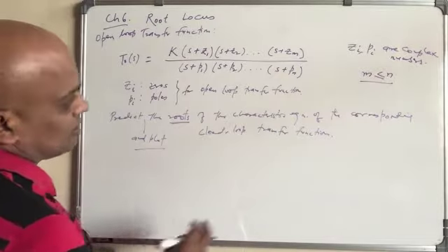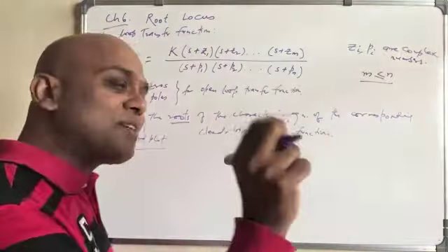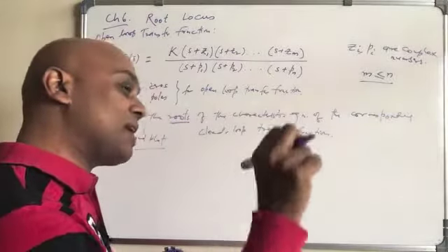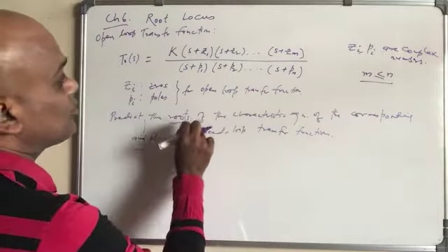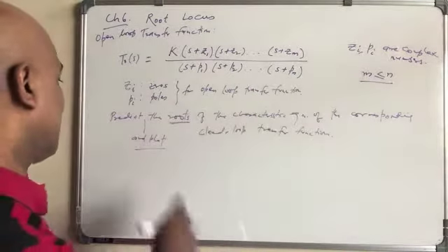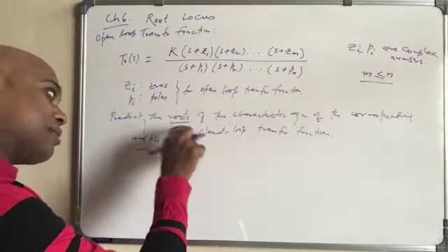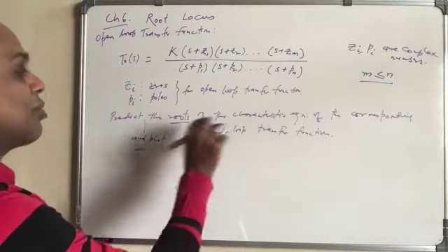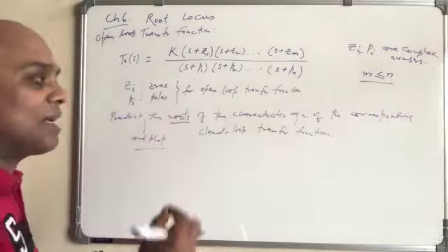And how do you plot? On the s plane we plot. We trace all the points on the s plane which can be roots of the characteristic equation of the closed loop transfer function. Of course those will be based on the k value. For different k values we have different roots.